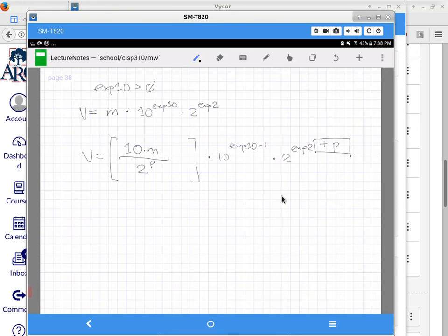What about that rounding thing? Do you think division by 2 may have issues with rounding? Absolutely. Because every time you divide something by 2 in an integer division, it can be exact, it can also be missing 1, because the remainder of division by 2 can be 1. So the whole thing about integer division having a bias to make the result smaller still applies. And we still have to do rounding. How do we round this? Same way, plus 1? Yep, plus 1 divided by 2.